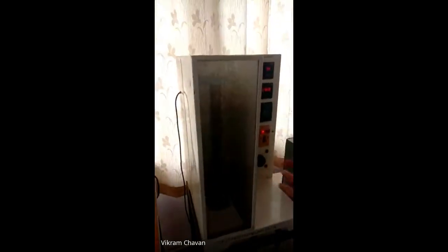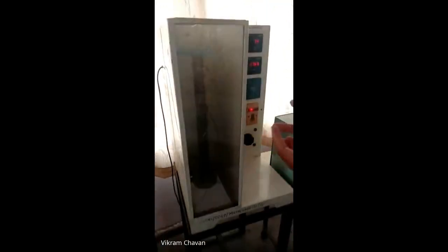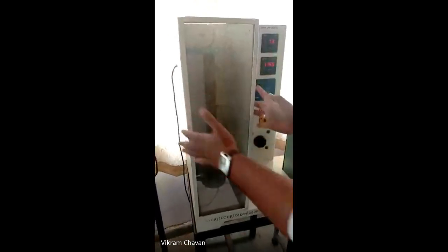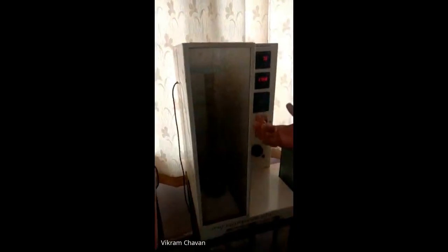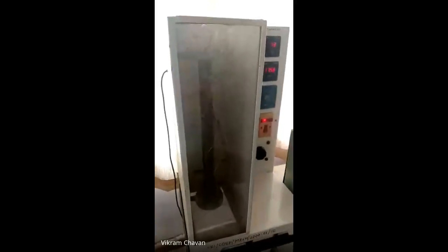There will not be any fluid movement or air movement because of any external agency. To maintain that still environment, this compartment is made. The front side is visible to you, so you can see the actual apparatus, and it is open from the top side, because whatever hot fumes or heated air there is will move in the upward direction, and to occupy its place the cold fluid will move upward. Once again that will get heated and move upward. That is the natural convection phenomenon.